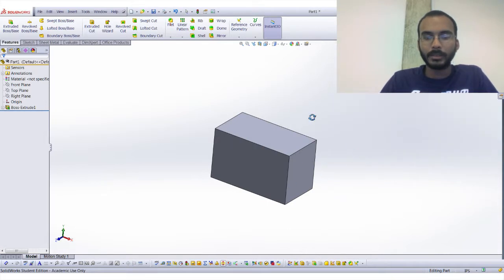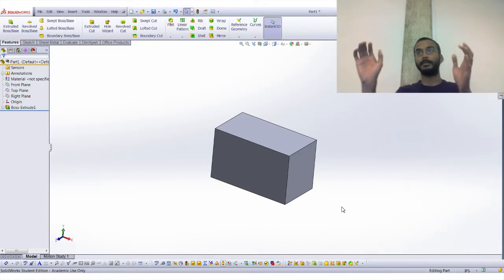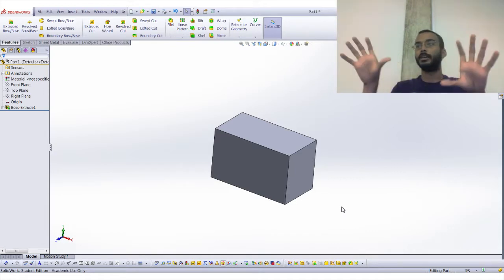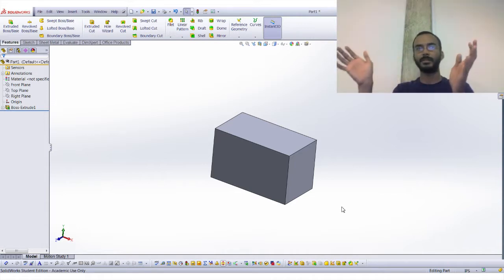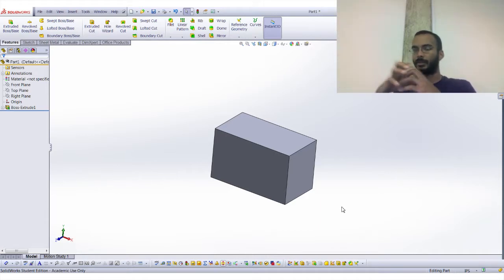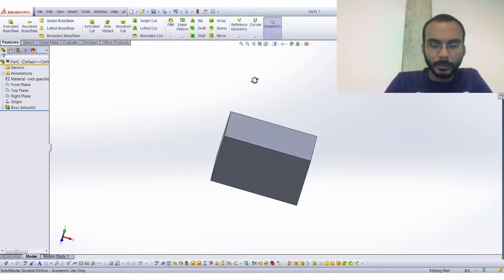Okay, cool. So this is the first three-dimensional part. Basically that same process of going into a sketch, drawing something, and then doing some other feature on it is pretty much the workflow that you do for most everything in SolidWorks. There's a lot of advanced stuff, but for the most part, you make a sketch, you do some sort of feature on it, either an extrude or a cut, or there's revolves, there's all sorts of different things you can manipulate it with. But that same idea, basically sketching, drawing out a shape, and then going in and actually extruding it and doing some feature task on it. What else can we do?